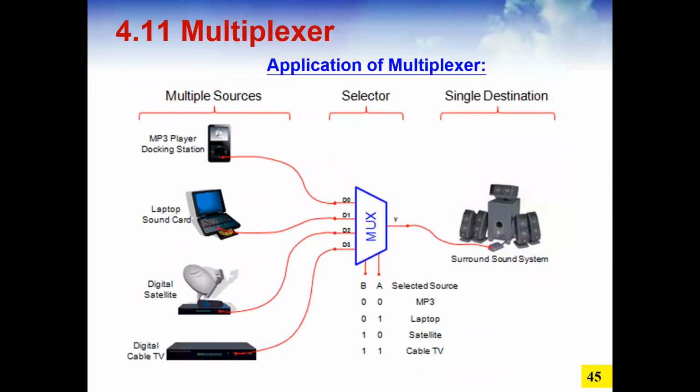Previous discussion. Next thing, in continuation of combinational circuits comes the multiplexer. And what is a multiplexer? A multiplexer is a combinational circuit which is used to select, basically to connect, one of the inputs to the output. It has multiple sources, multiple inputs. And how many outputs are there? Single. And how is it connected? There is a selector.